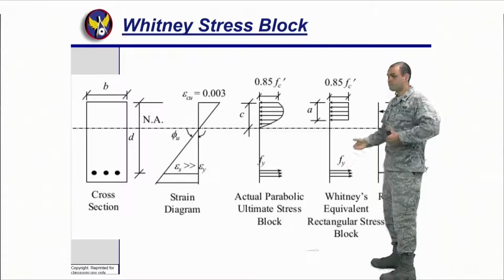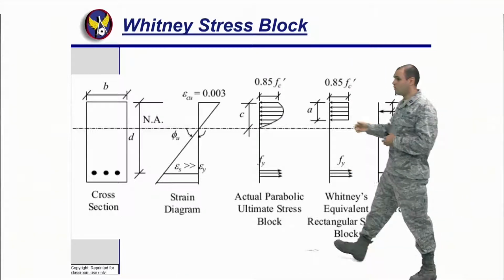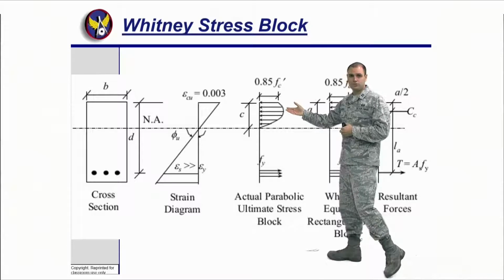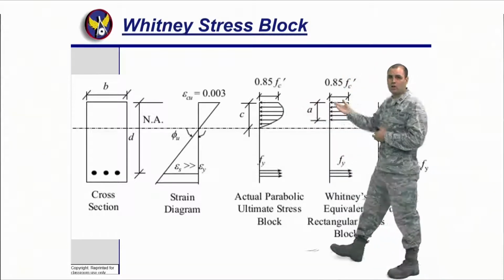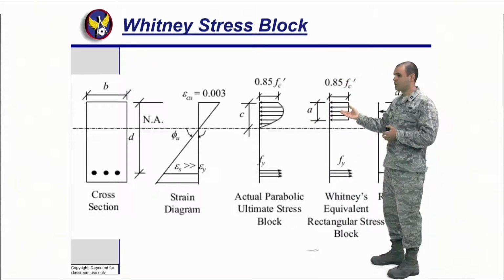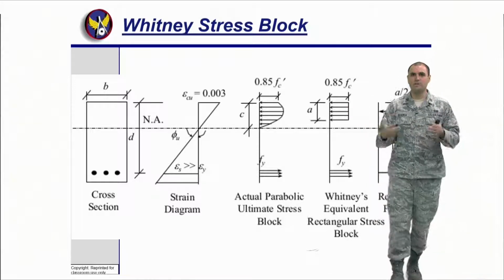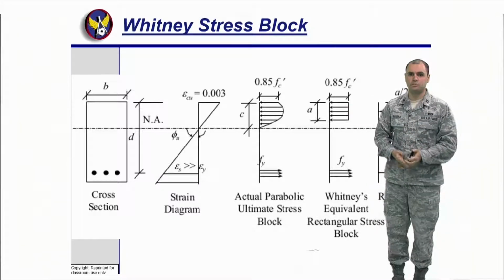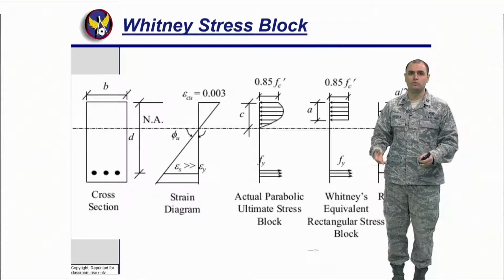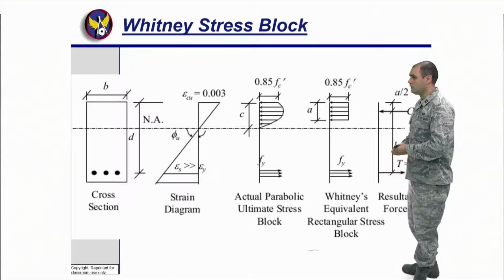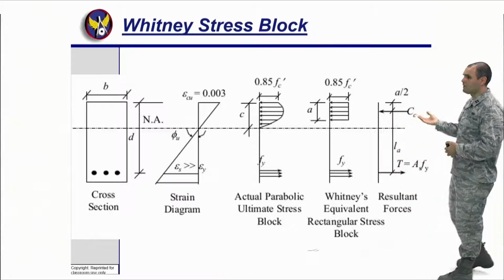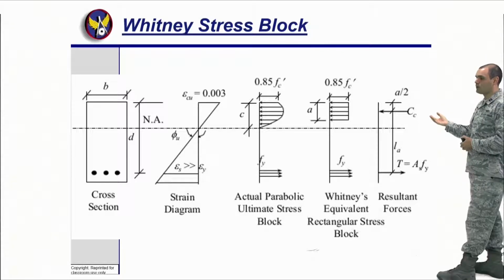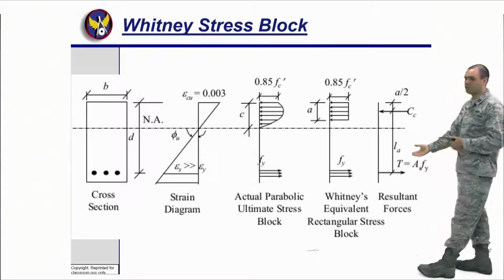In the end, Fy is still there. Even though the actual stress distribution is nonlinear, we're going to assume it's linear, just like you see here, just for our sake, to make our calculations a little simpler. We don't want to have to do calculus every time we do a design. And finally, we're going to make sure that we have a compression strength and a tension strength, As Fy.